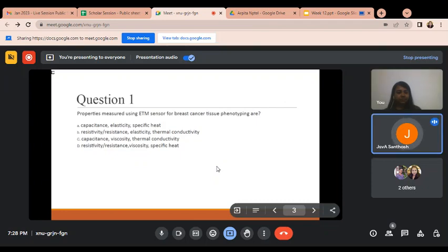Ma'am, could you repeat the question? Where we are taking the source material, this is called the boat or the source holder. It is also a metal boat. So if the melting temperature of that source holder is lesser than the melting temperature of the source material, then what happens in that case? Think and then tell.